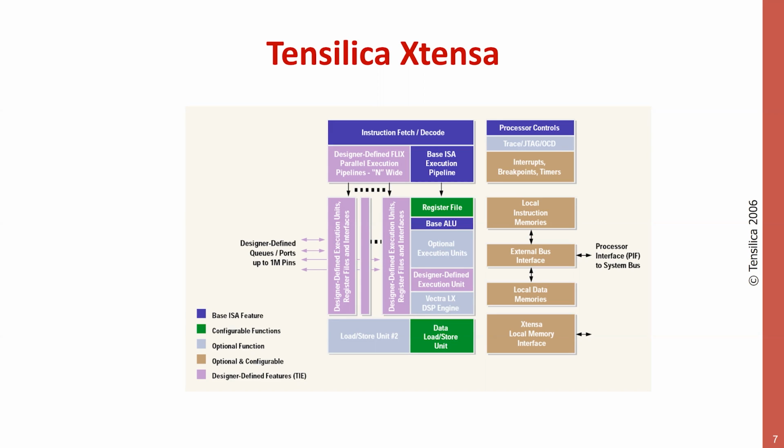and you will get something that is the composite of what you see in this image, right? You see the blue and the green part, and if you read in the little boxes, what you imagine is a simple RISC architecture, right? It has a fetch decode unit, it has a basic execution pipeline, it has, of course, register files, some ALU, a load store unit, whatever you need, right? The basic things that you need, control stuff. And this every processor needs.